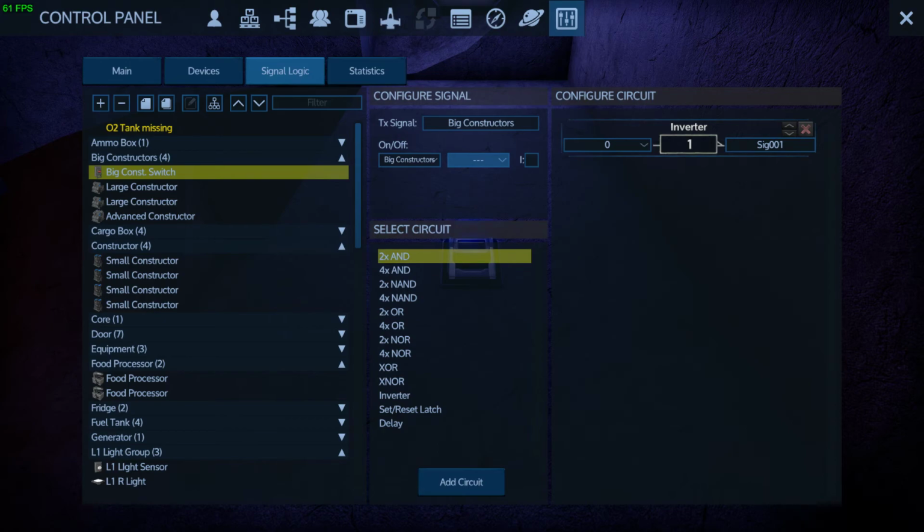But now with the switch, there's a number of positions for the switch. There's straight on, to turn the switch on and it's going to be constantly on, or you can have it constantly shut off. Toggle will let you turn it on and off, but it kind of wastes a whole extra step. Follow is the most convenient, so we're going to select follow, and basically the signal behavior is going to follow the position of your switch. So we're going to select follow.